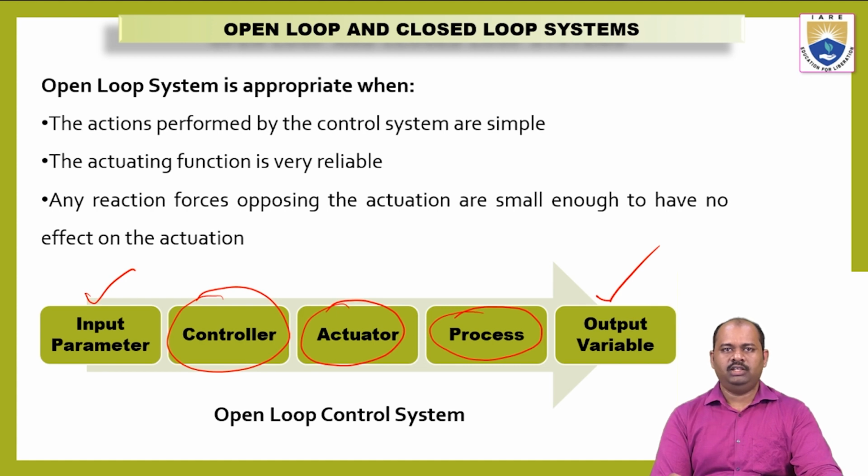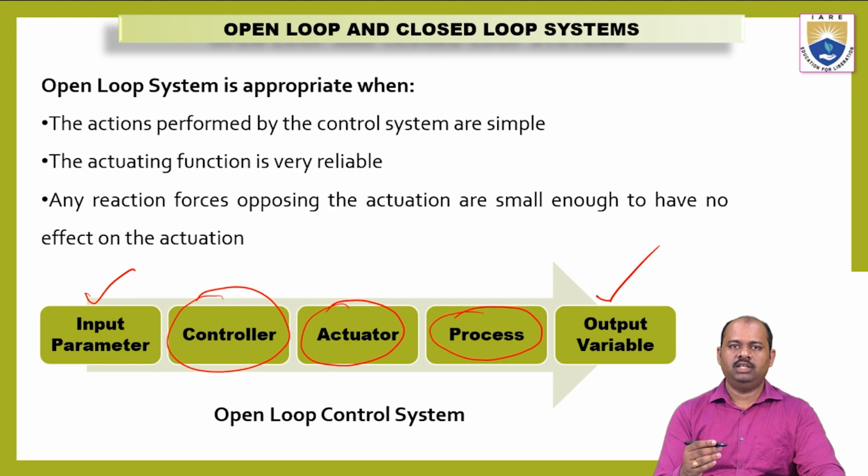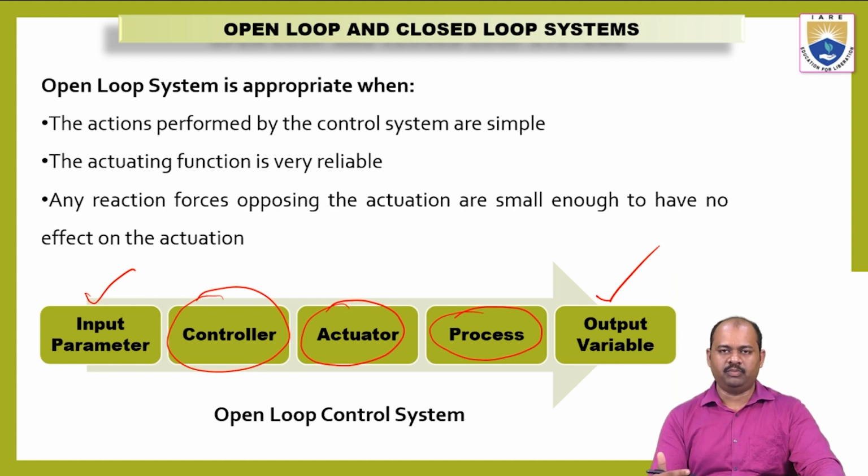Now when the lathe is turned on, the chuck will be rotating at a speed of like 50 rpm or 100 rpm. Whenever the chuck is rotating, we will take the tool post along with the tool near to the workpiece. What happens is the material from the workpiece is removed by the cutting tool. The cutting tool will remove the required amount of material from the workpiece.